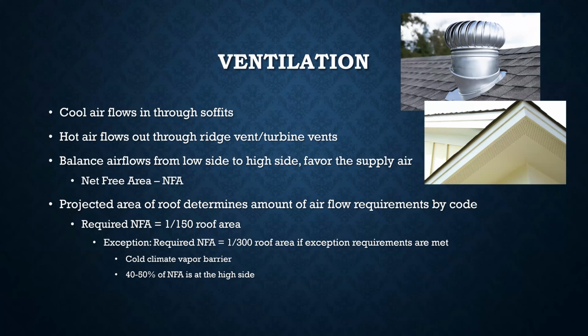That's not quite the important one. The more important one is that you favor the low side of the ventilation. The way they say that is 40% to 50% of the net free air is on the high side of the house. If you do that, then you are allowed to only ventilate 1/300, and that's sufficient ventilation.